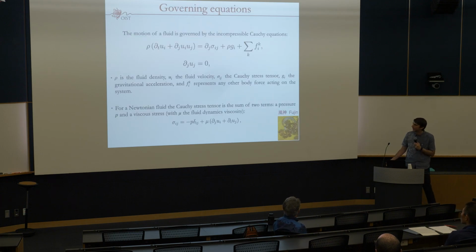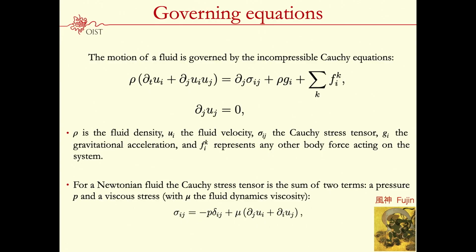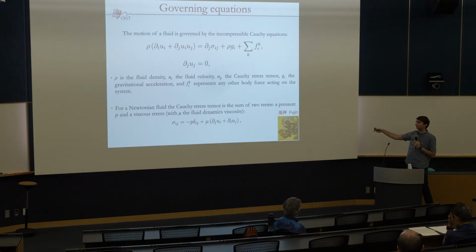Let me see. So in terms of equations, all of that, I didn't go through, but so this Cauchy stress, for Newtonian fluids, basically we have only 2 terms, 1 pressure and 1 viscous. If you want to do more complicated fluid, for example, later I mentioned polymers or EVP fluids, those are called non-Newtonian, and basically you have extra terms here on this Cauchy stress. So the equations formally remain the same. What changes is the definition of your Cauchy stress, which will have additional contribution.